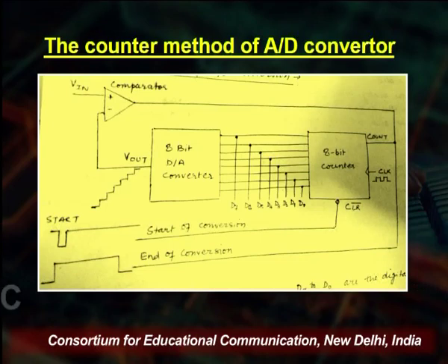For low current analog inputs, we have specific operational amplifiers, and the one that we have discussed in our earlier lectures, that is the 741, would not suffice the requirements of this circuit.